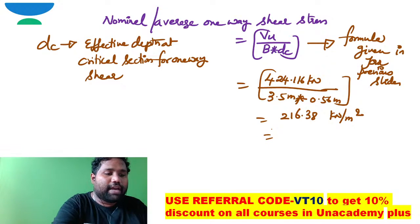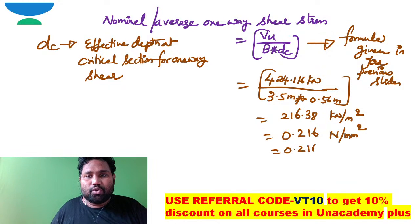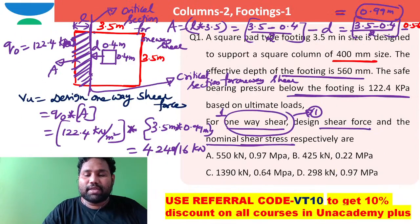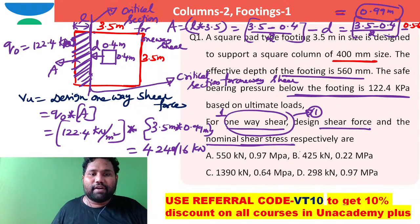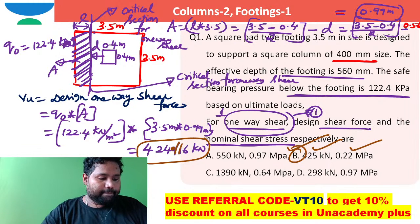If I want to write it in terms of megapascal, I can write it as 0.216 megapascal. Megapascal is Newton per millimeter square. So if you see the options, the one that matches is 0.216 megapascal. I hope you are clearly able to see 424.116 as the answer in kilonewton, and the stress is 0.22 megapascal. The correct option is B. Is that okay? So shall I move to the next question?